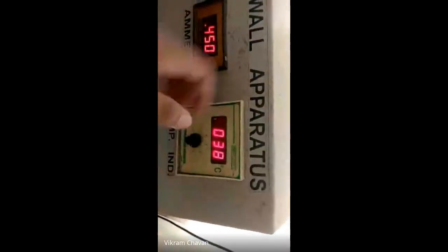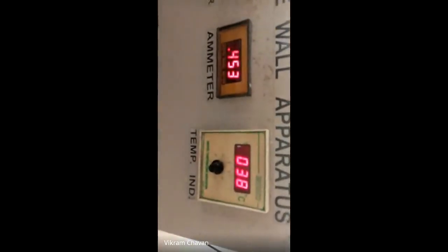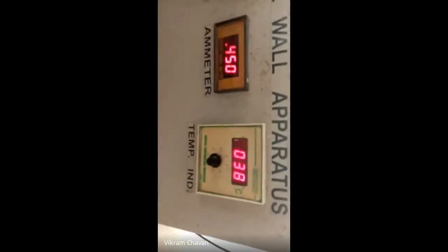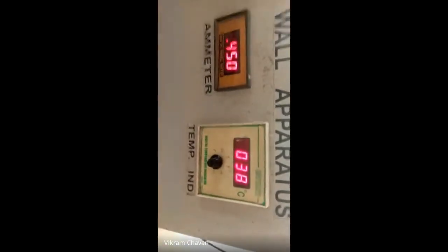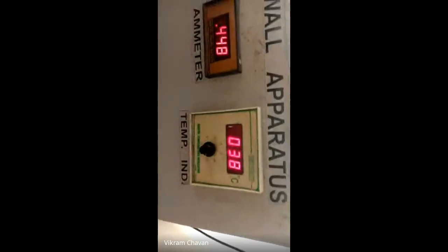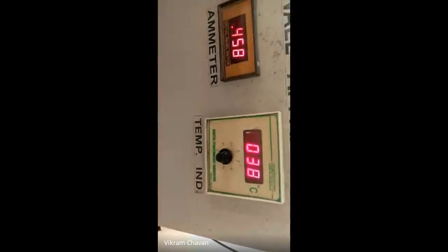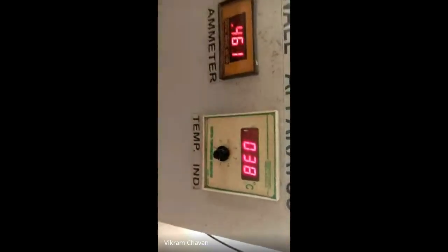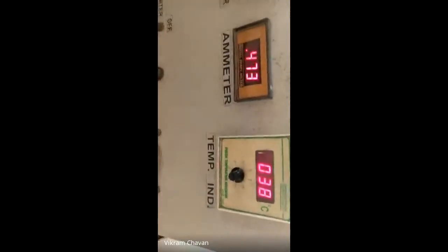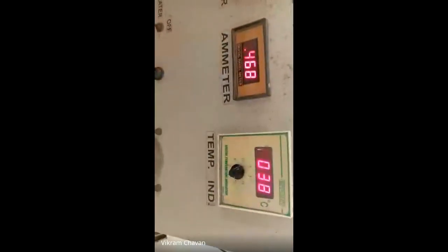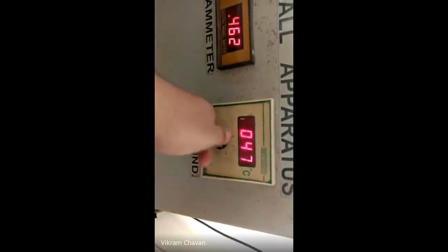So this is the first reading, and we have to perform this experiment for steady state temperature. Steady state condition means the temperature will not change with respect to time. If the reading is repeated after the next 5 minutes, then we consider that reading as the final reading. Until that moment, we have to continuously take the reading after each and every 5 minutes. Is there any doubt, any question?